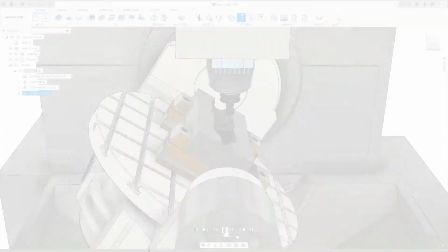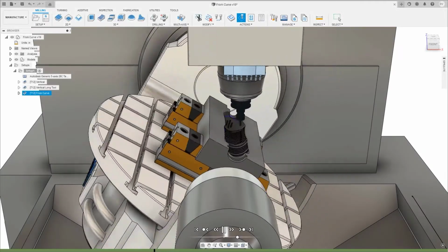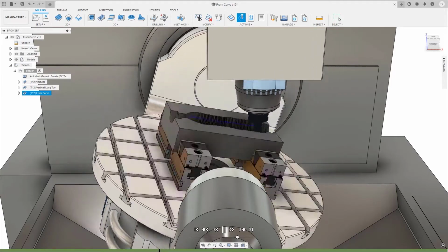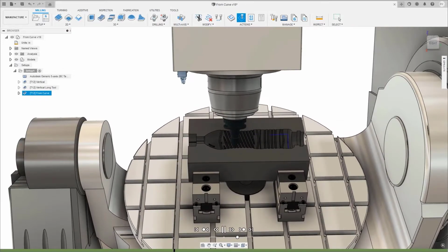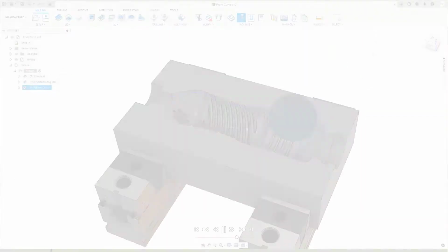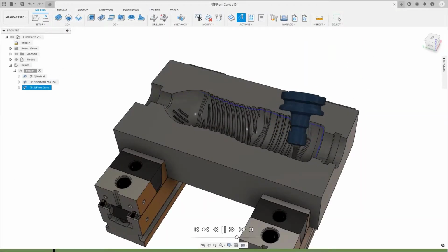To help with this, Fusion 360 has a range of tool axis definition options which can be predefined during the CAM programming process, simplifying your workflows and resulting in quicker success. Here we are going to look at how a tool axis can be defined so that its orientation is aligned from a curve. This often works well on part shapes where the curve follows the form of the part. In this case, the bottle mold cavity has a predominantly linear shape to it.